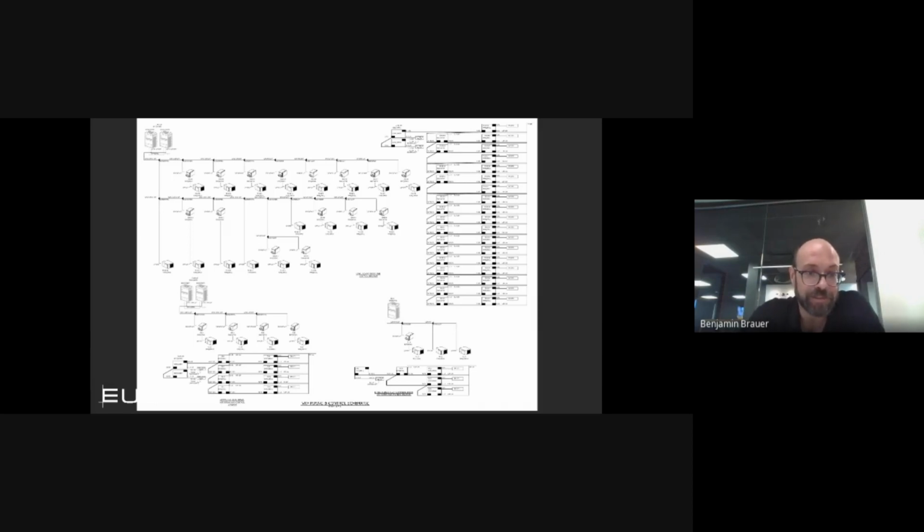It's a pretty slick system in this case, but every floor required a mechanical room to place those outdoor units, which you see in the top left corner and middle left there. But they were able to achieve one more level of tenant occupancy space because they didn't have a plant room per se for the major mechanical equipment such as chillers and boilers and such.